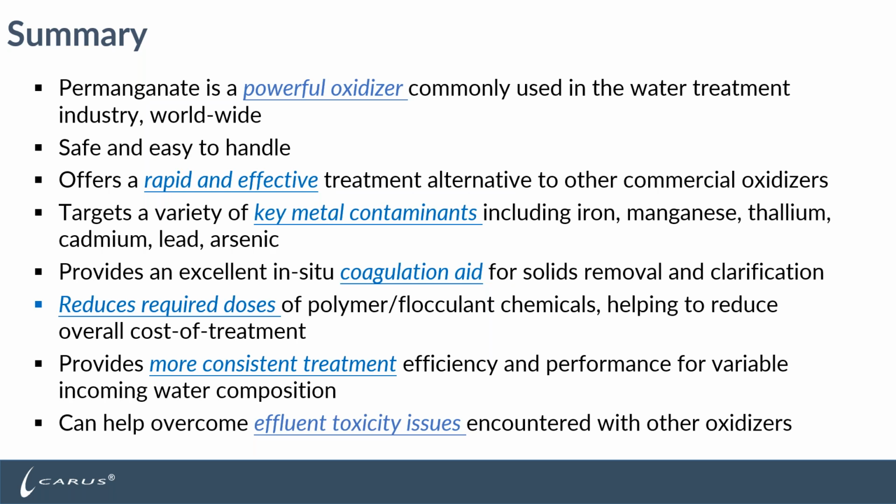The reaction provides an excellent in situ coagulation aid for solids removal and clarification. This MnO2 that we produce can also reduce the required doses of those polymer and flocculant chemicals, helping to reduce the overall cost of treatment. It can also provide a more consistent treatment efficiency and performance for incoming water composition that can be quite variable, and can also help overcome effluent toxicity issues encountered with other oxidizers.